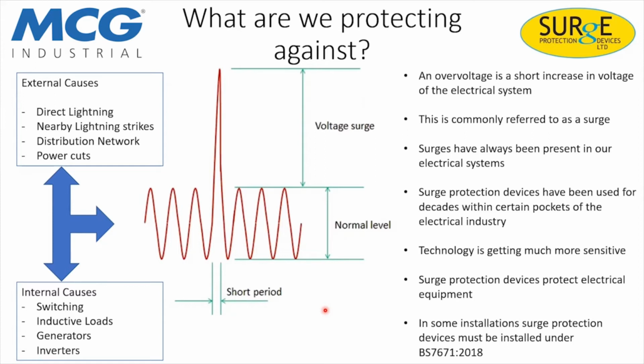We also have surges that come from inside of our property, and this is something that most people aren't really aware of, but actually up to 80% of surges can occur inside the electrical installation. So we have things like switching surges, which literally are as simple as they sound. Every time you flip a switch and pull a load, you create a surge in the system in varying degrees. We can have inductive loads, generators, inverters, air conditioning units, lifts, all these sort of big pieces of machinery, as well as our tiny little piece of machinery that we use in our homes, like the DC drivers in your washing machine, all create surges in the system.